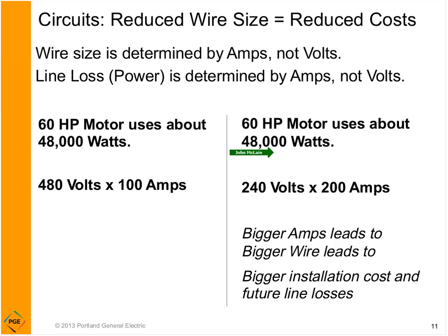You would think on the electric bill, those are the same, and they are. However, remember we talked about the volume and the garden hose size. More amps means bigger wire size. If that's copper, you just doubled or more than doubled the cost of the materials to install this piece of equipment. If that piece of equipment is on the other side of the building from the service to the electric company, you might have a pretty long run of copper. Also, line losses are a function of amps, so you could even have a voltage issue the further away you get from the panel.